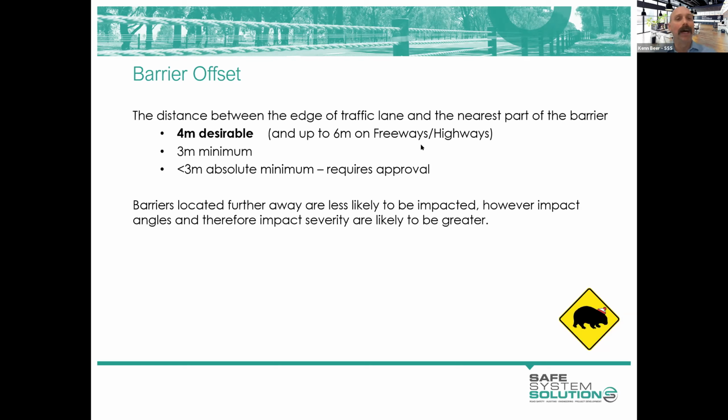And it also is taken into account in where you place breaks in median barriers, if you have incidents and you need to counterflow and operate the road in different scenarios. So it's really not something that you can just say, we're going to go this offset and we're going to do it for 20 kilometres and we're going to break it only every 2 kilometres or something like that. There's more detail to it, and there's a lot more work in the design required for that.